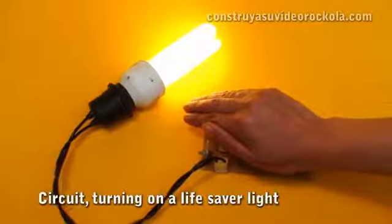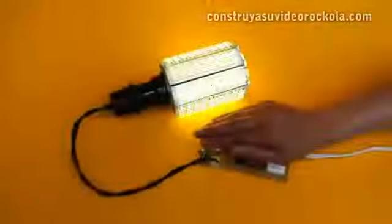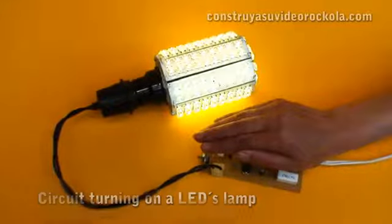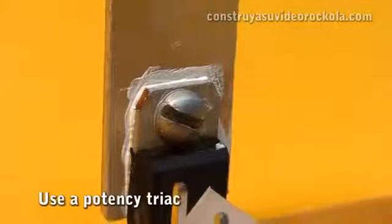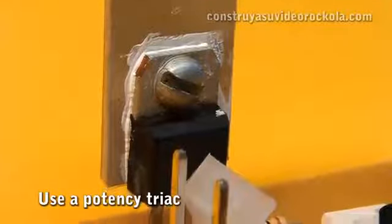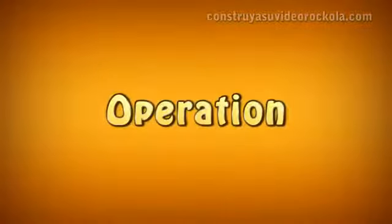This circuit operates with voltage from 115 to 220 volts, no need to make any changes. You can light a bulb up to 100 watts. If you want more powerful lighting devices, you should only change the BT136 triac for one that supports more amps, such as the BTA08-600, which supports up to 8 amps. Operation.